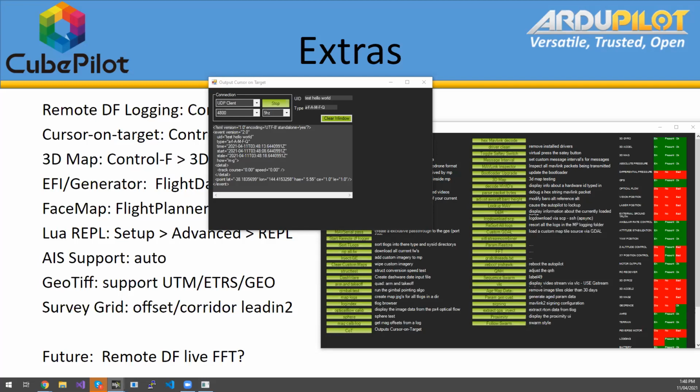It works with antenna trackers too. What I have right now is I use this feature where I get the data from the aircraft on MAVLink, and then from here, I can forward this to an antenna tracker that only talks cursor on target. It's kind of like forwarding NMEA, where you forward the GPS information, but this also allows you to broadcast information to other devices. So people on other networks would see your aircraft show up as a device. And soon I'll be adding this natively into ArduPilot itself. Yep, I just connected to a vehicle there so we can see real latitude and longitude as an example. So that's basically live now to some extent. That's what it would look like in real time.